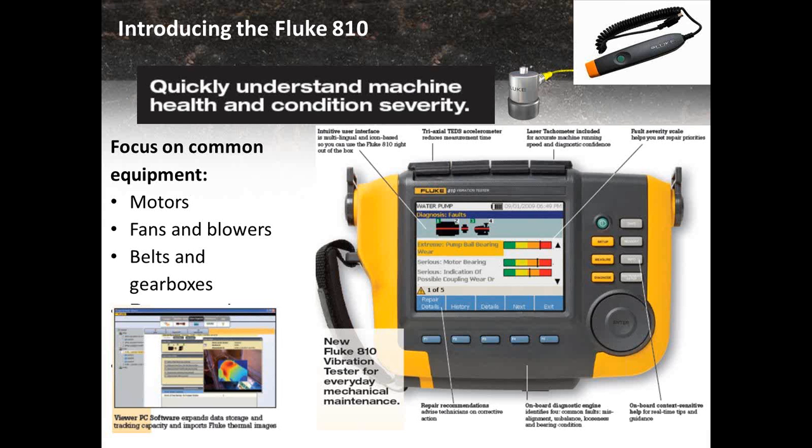How often do I need to go and make a diagnosis of a machine? Typically, there are a lot of different parameters, but I've been doing this for over 20 years. Most machines would be monthly. Sometimes you've got machines that just don't run very often, and quarterly would be okay. What we typically recommend is monthly, and quarterly is the outside. Based on how long your machine is running and how critical it is, you would go somewhere between monthly and quarterly.